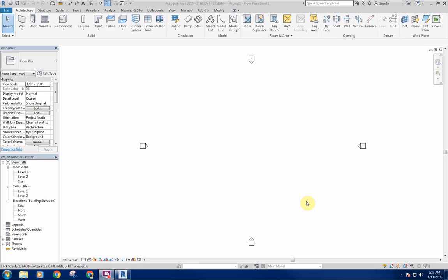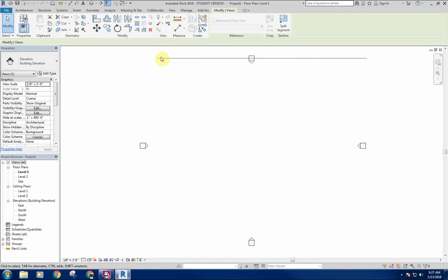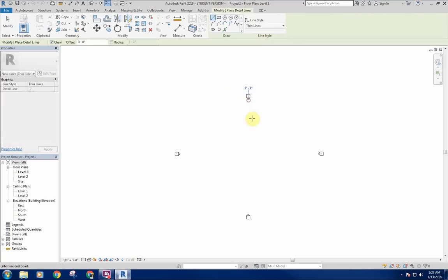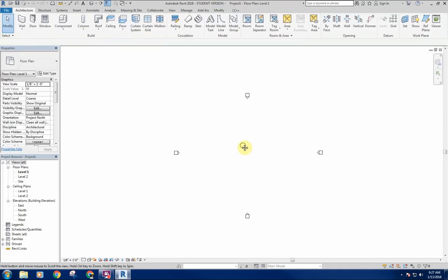So first things first, this is Revit 2018. If you create a new project with the architectural template, this is what you start with. You don't have a lot of room here. These carrots here, these are your elevation markers. So if you get beyond here, this is going to read as a section rather than an elevation, and we don't want that. So basically they give you, let's see, in between here, like 130 feet, which is fine.